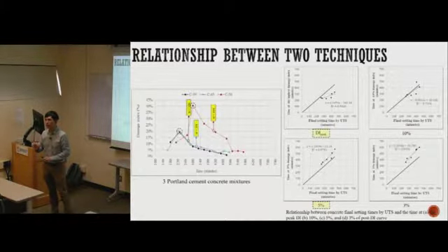I use 100 images, and two consecutive images must have at least 50% overlap. So two images will find the same features, right? And then you have 100 images. Those features will build the common points and start to build the 3D point cloud along a cut.